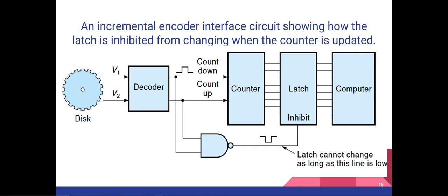In many applications, this resulting error can be ignored, but in other situations, it is required that data should be accurate. So one solution to this problem is that we can freeze the counter during the time when the computer is receiving the data. However, this is not an effective solution, as when the next clock pulse arrives, there would be a possibility that the data will be permanently lost.